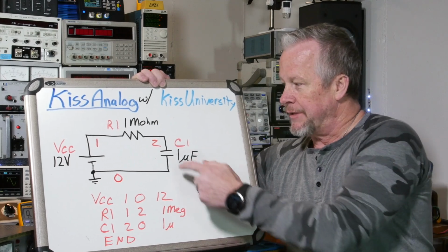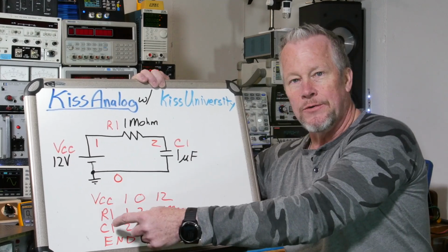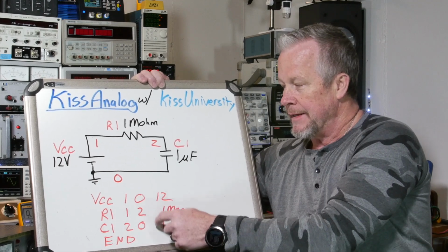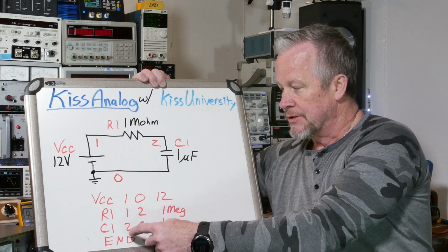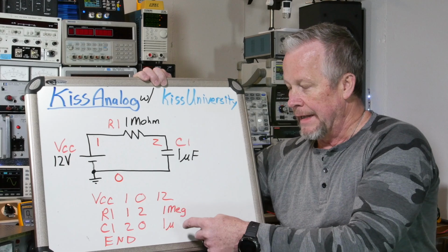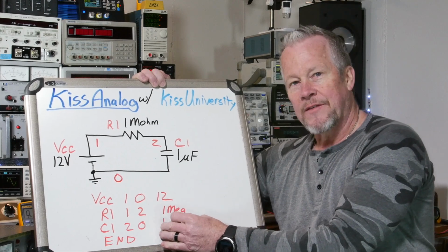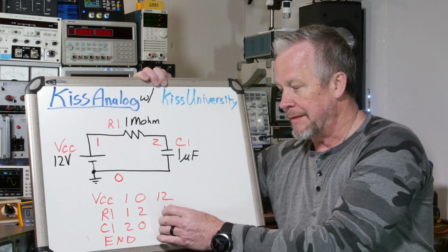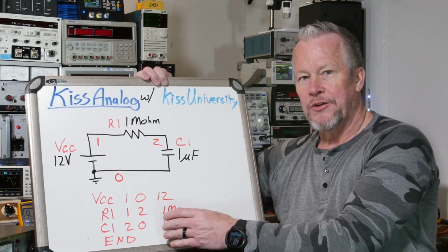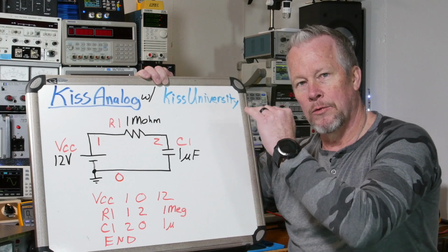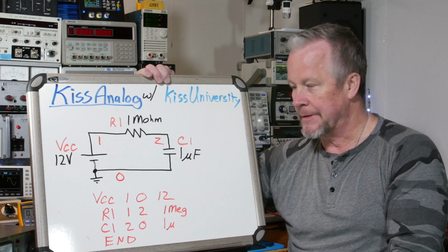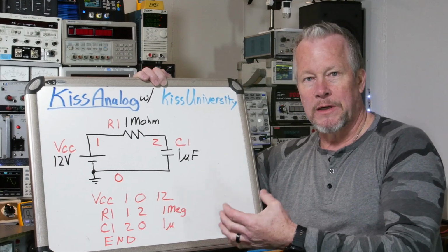Now you can imagine if there's a transistor in here, it'd start with the Q, and then it'd have 3, because it's a 3-pin device, so it'd be 2, 0, 1, let's say. And then after that, because it's a model, it would say Q model, and in that Q model there'd be a whole list of statements like this, what's inside that Q model, okay? Sub-circuit would even be more complex.